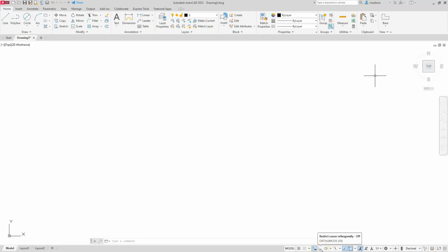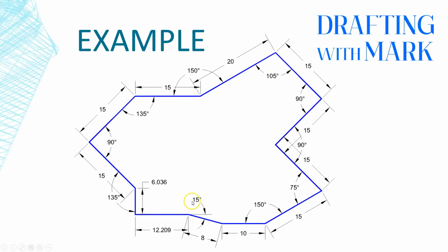This one, you can see that there's angles all over the place, and there's a common theme with all of these. If you're not too familiar with them, all of these dimensions are at some kind of 15 degrees. That's going to tell us what we need to do when we set up our polar tracking. This is a perfect example for when to use polar tracking. We have the angles and we have distances, so on this one, we will not need to deal with any kind of rectangular components. All polar tracking. And then, like I said at the intro, we're going to deal with these two lines here by using the object snap tracking. So we're going to get that going.